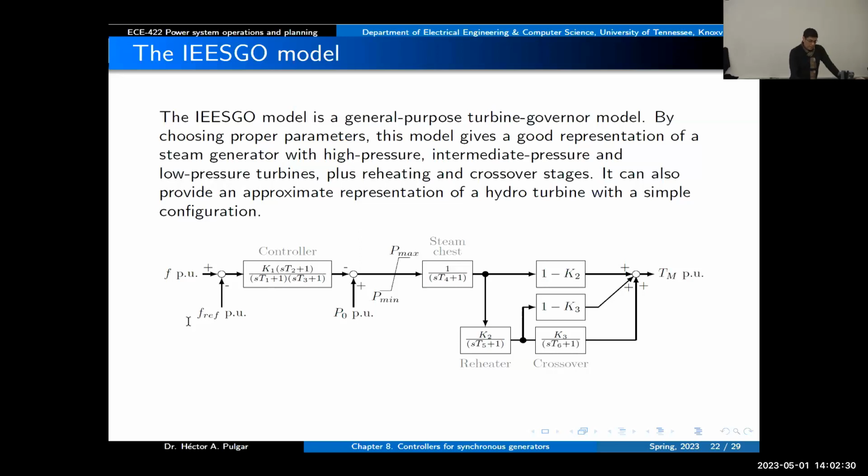But then you will have poles and zeros that are typically studied in control system. So in this case, we're going to recognize that the poles that you have in the transfer function are going to be related with eigenvalues in your system. Yeah, the eigenvalues, then we have some characteristic about the stability and how the system will behave dynamically. Well, you get the same information from the poles, which is the denominator that you have in this block in this diagram.